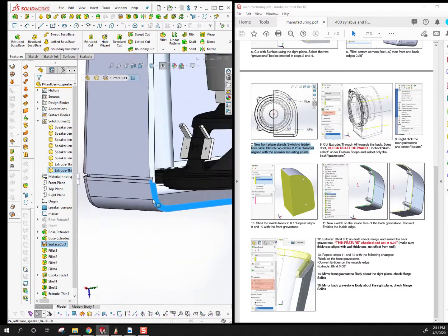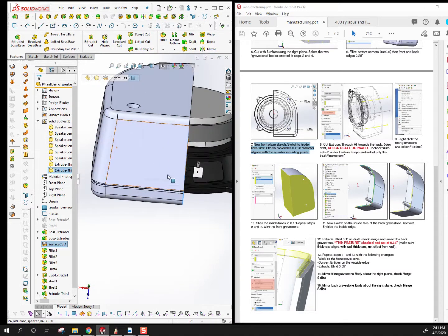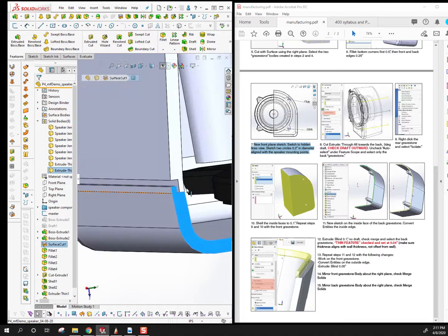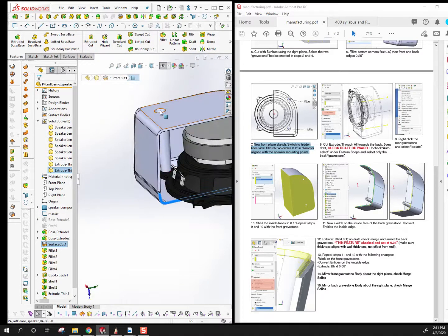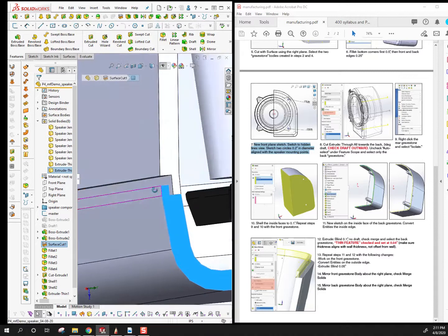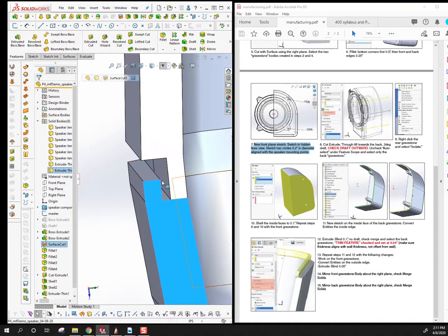If you imagine, once we mirror this, taking this back piece and trying to slide it left and right, this outside wall is going to capture that, and it's going to prevent it from sliding apart. So that is a way to secure the attachment. If we then have a boss or a screw that screws the back plate to the front plate, or the back body to the front body, this kind of puzzling feature of having the outside wall trap the inside wall will help add to the strength of the object.